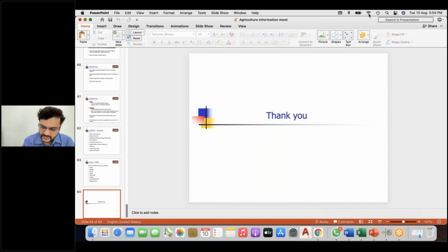But if you set up a small capacity line, sir, of say 500 kg per hour of mangoes, then the output is just about 200, 250 to 300 kgs per hour. Or even in case of tomato puree, it would be like 100 to 150 kgs per hour. In that case, the number of cans is only about 5 to 10 cans per minute, and you can easily handle it with the help of semi-automatic machines. So the cost which I had mentioned includes all the machines, including the filling machine, etc.